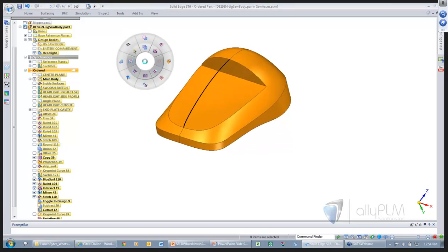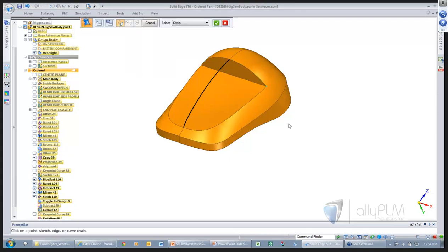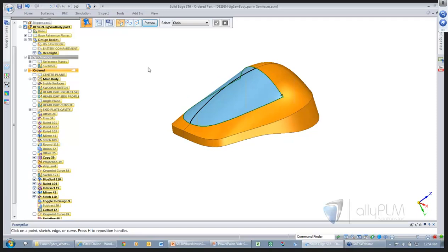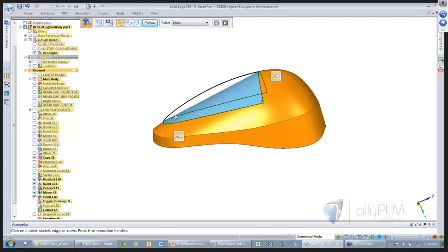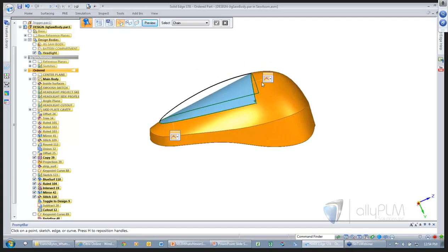That key point curve. So I'm going to create a BlueSurf using the model edges. Now right now you'll see that it's just that linear natural extent. Now my controls, because of how they butt up next to the other surfaces, I do not see tangent continuous or curvature continuous. But I have it in my curve, right? We just saw that. So I'm going to pick that curve as a guide curve. Then that will give me the control desired.